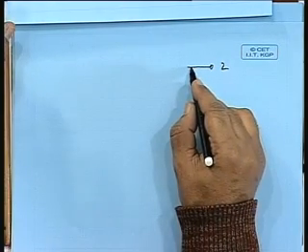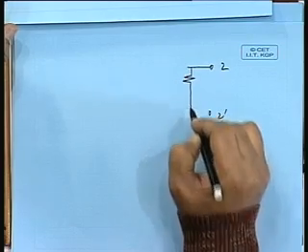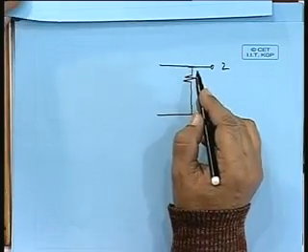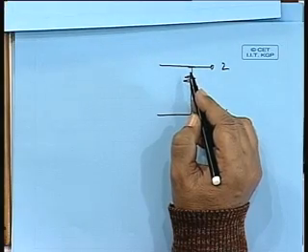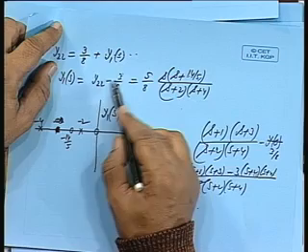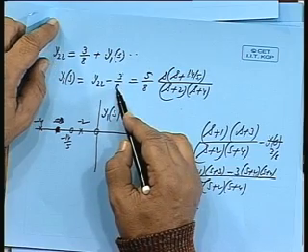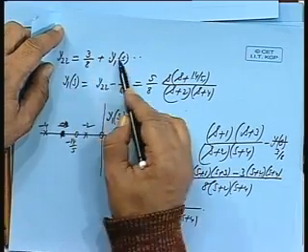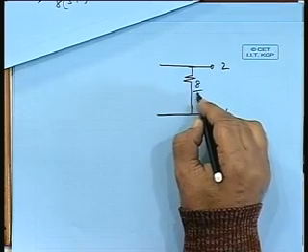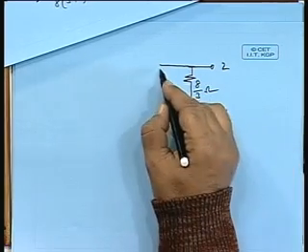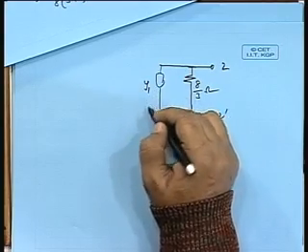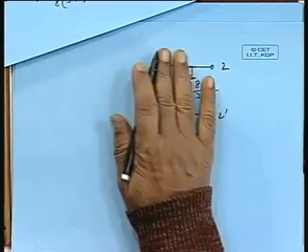We have started with a first element which is a resistance. 3 by 8 is a constant that I have removed. y22 is equal to 3 by 8 plus y1s. So, 3 by 8 is the admittance. So, 8 by 3 ohms resistance I have put, and this is the balance y1s, yet to be realized.